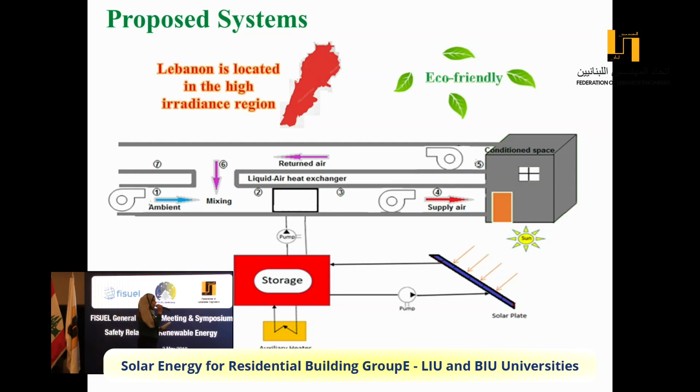For the solar heating system, in the coastal region the summer is tough, but the winter is moderate. So an air-liquid heat exchanger is enough for us, because the heating load is about 9 kilowatts, while the cooling load was about 27 kilowatts. For the energy-saving target, we mix the ambient air with return air, because the sun irradiance in winter will be low.